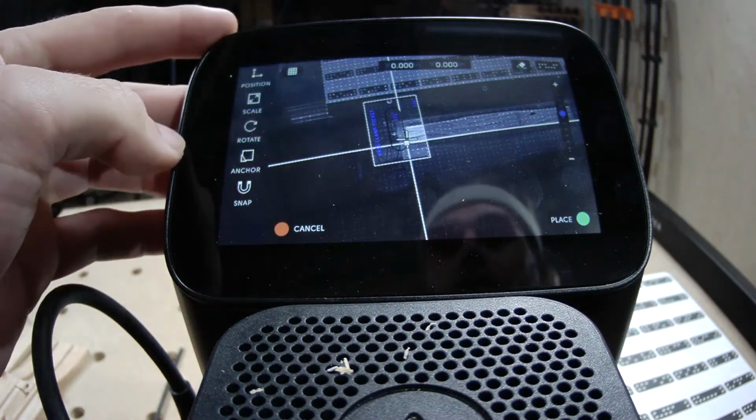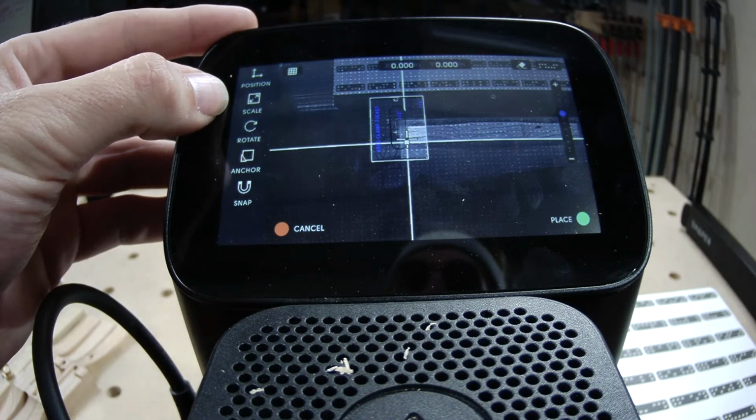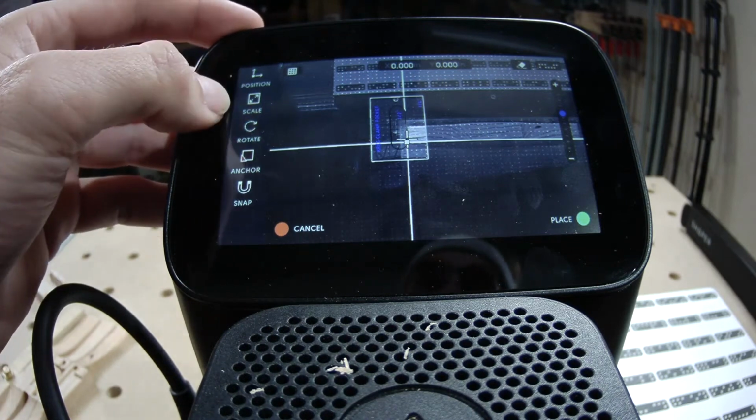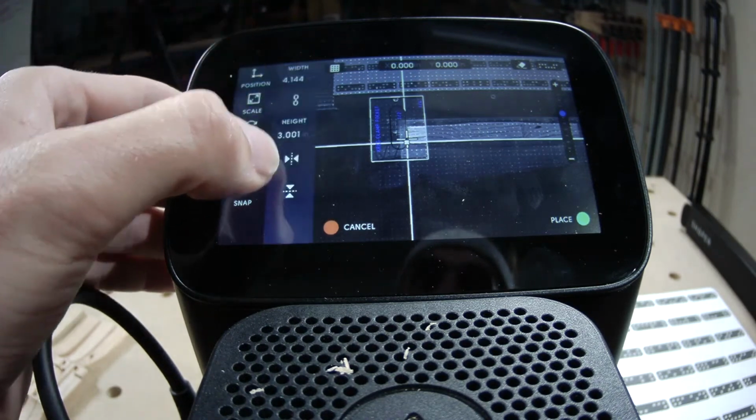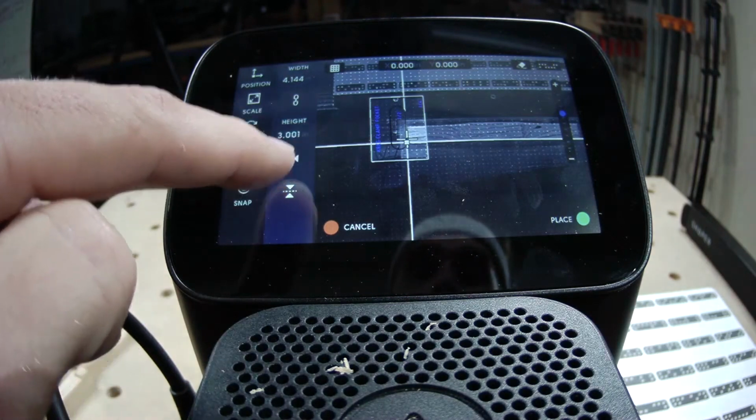Yeah. So this is actually a great one because we haven't really talked too much about mirror yet. So mirror is now a new feature under the scale menu, and it's these two buttons here. And when you click them, it just mirrors that object. So if you have to cut some piece that is alternate of the other piece, like the inside of a drawer that needs to match, you can now do this directly on tool by clicking these buttons.